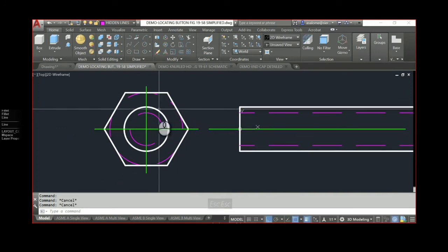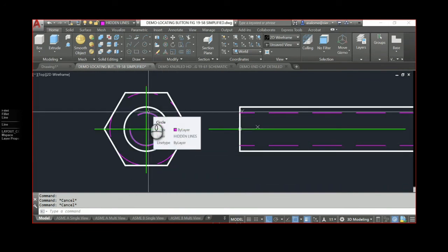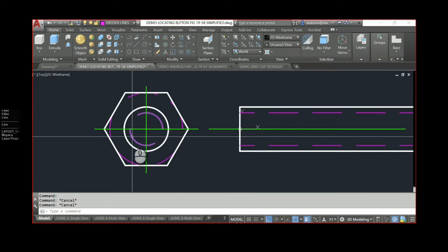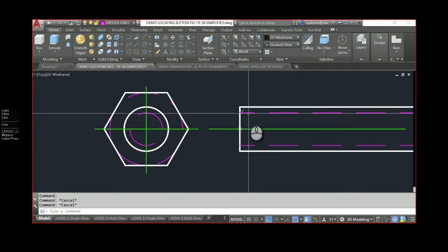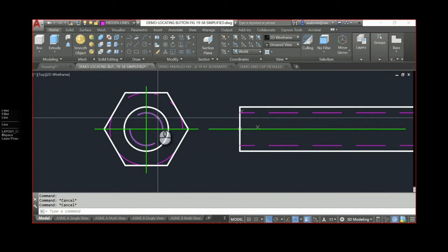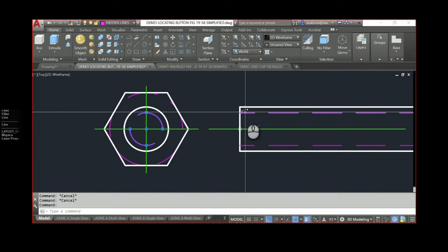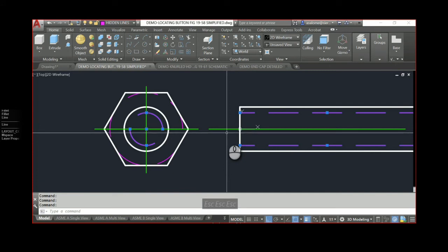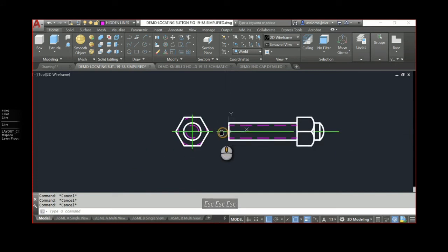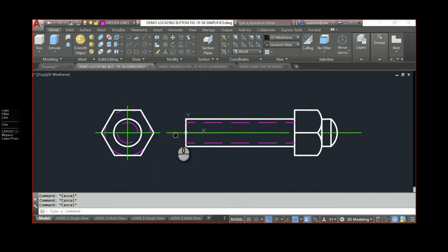If I'm looking at the end of a screw, the object line that I see is at the crest of the screw thread. And what's hidden from me is the V cut down to the minor diameter, or the root. So if that were a hole going through this part, this would appear as a solid visible line. But because it's hidden from my view, it indicates, along with this data over here, that it is indeed screw thread representation. Now, of course, you're going to have to call that out. You're going to have to do that with a thread callout.